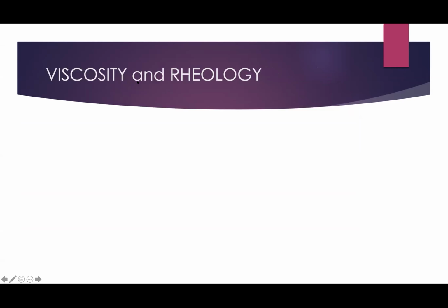So we then move on to liquid friction, which is known as viscosity, okay? Viscosity is basically the internal friction of a fluid. A shear is the force required to move one layer of fluid relative to another. So a shear will occur, for example, when you shake a liquid or pour a liquid out. And basically, the more viscous a fluid is, the more shear force you need to move each layer of fluid relative to the other.